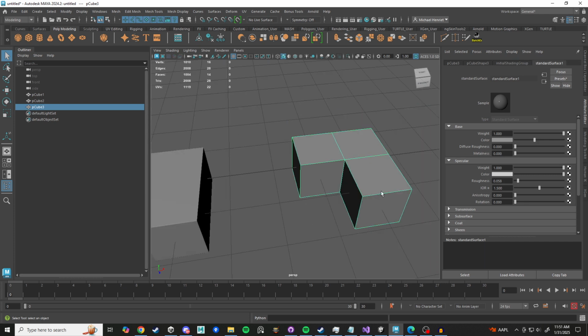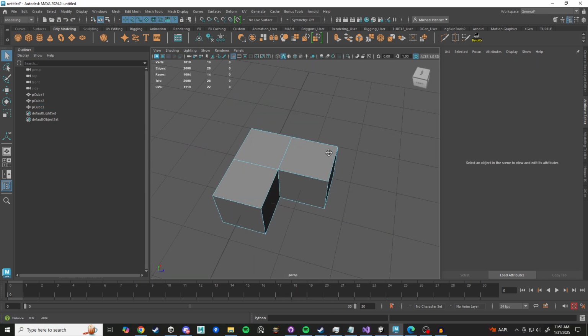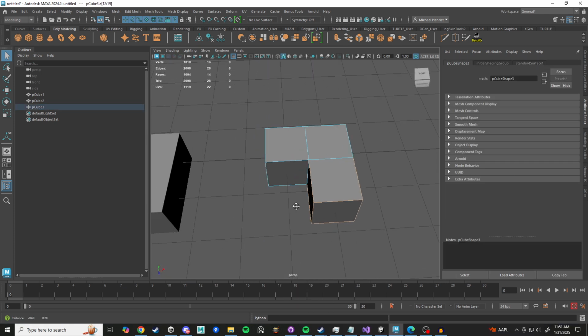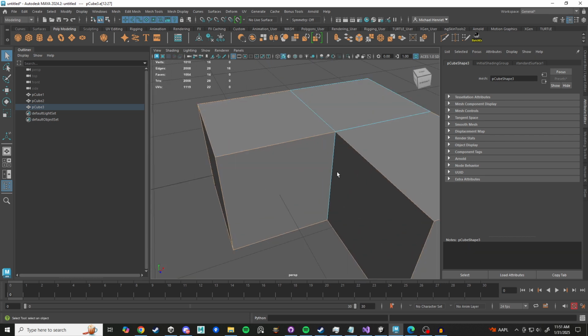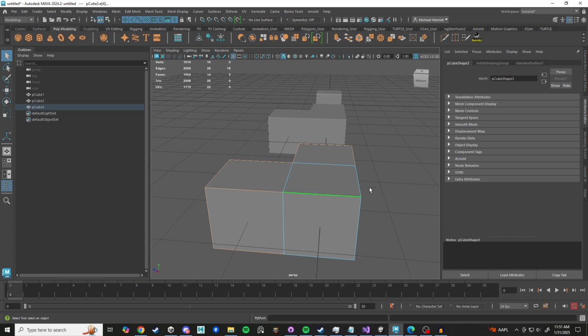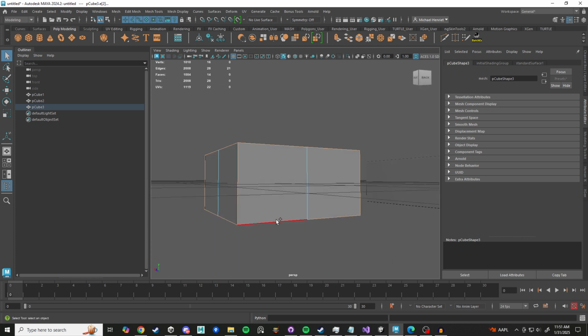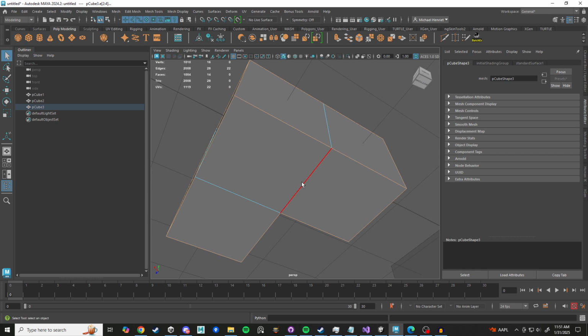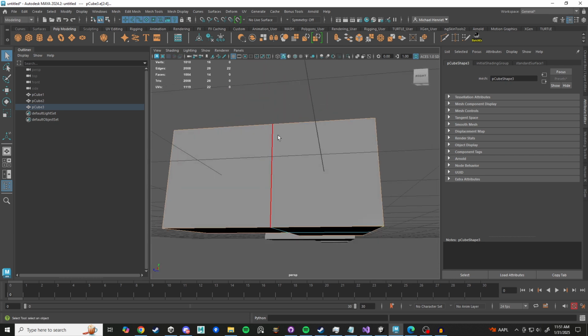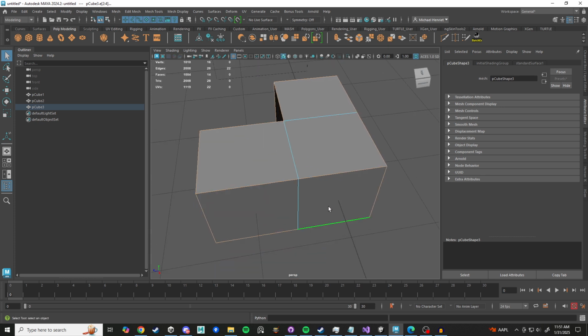So one thing I'd recommend is be more careful with your bevel, right? So I'm going to grab these edges, this edge, and these, right? So note that I have left out these edges, right? These ones are just on those flat faces. They're not going to retain anything, right?